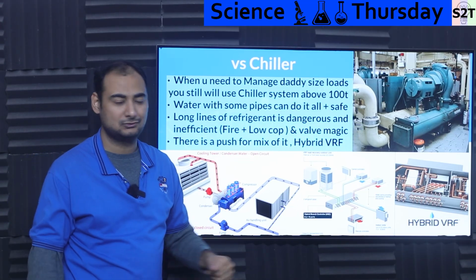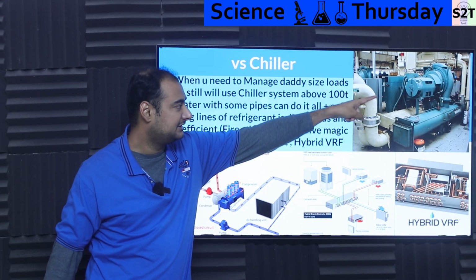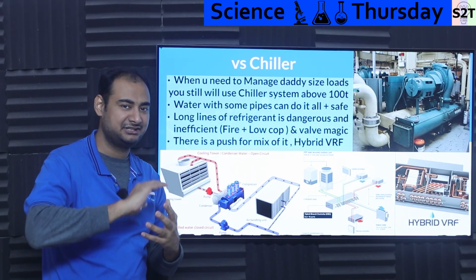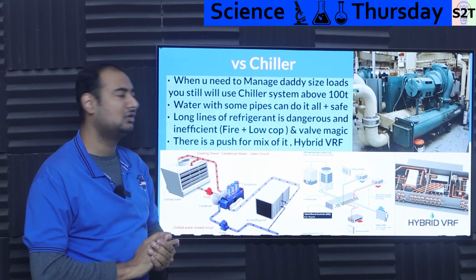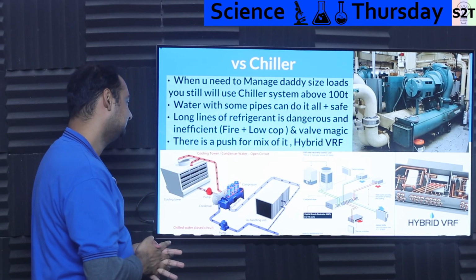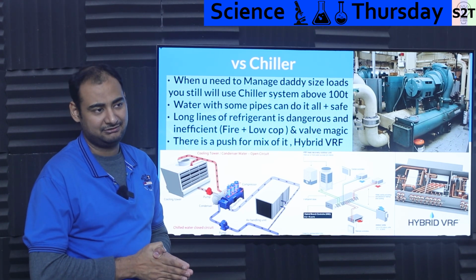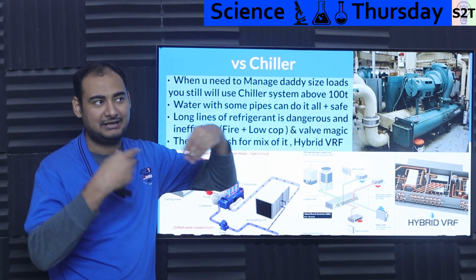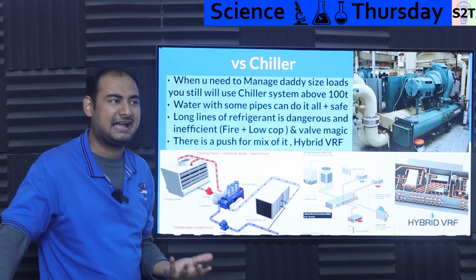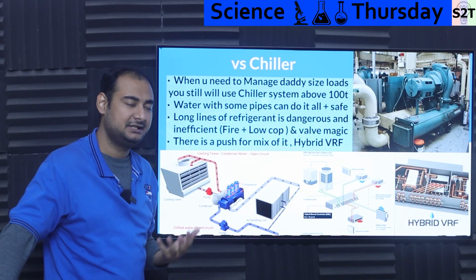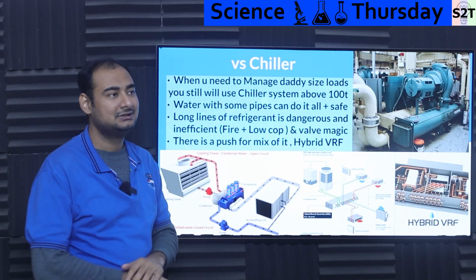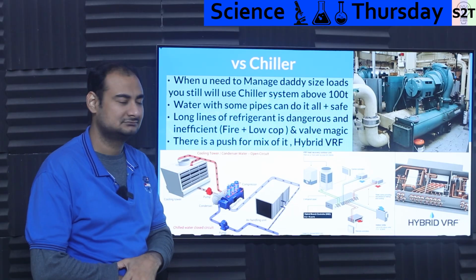Second, everything is closed loop. As in, you have condenser here, evaporator here, compressor there, a valve there, the end, go home. Everything is tight. So all the phase change is happening in tight loops. So you get a lot of very effective coefficient of performance. That's the good part. And you can achieve what we call heating and cooling in this also. It's just extra plumbing, but it's not impossible. It's hassle. It can be done. It has been done in many scenarios and has been done from decades ago. It's just that it's hassle.